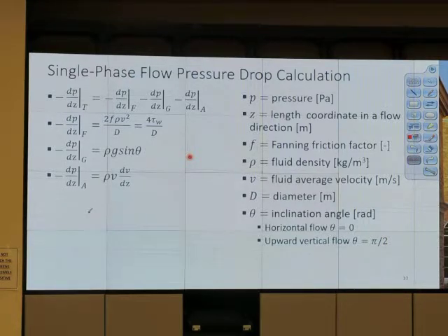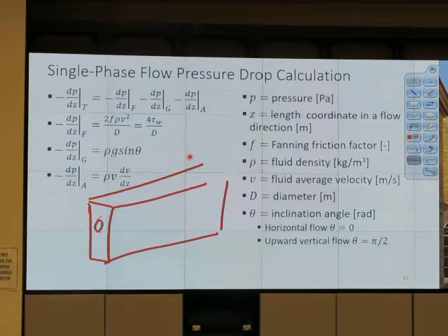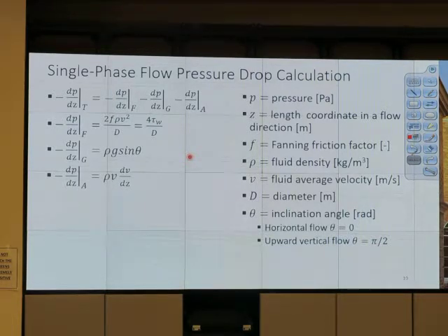But I did a test. I have a rectangular shape, so it's like a duct like this. But the inlet is just a circle shape. So I have the flow going here. What happened is the fluid goes into the entering point, it kind of expands to fill everywhere, right? And then it flows along the rectangular duct. So what happened is when there's an expansion at the front, I observe a pressure gain. Okay? It's like it flows slower at that point. So this means whether there is more pressure drop near the inlet or not depends on the inlet condition, how the inlet looks like. So it's kind of more detail on that. All right.